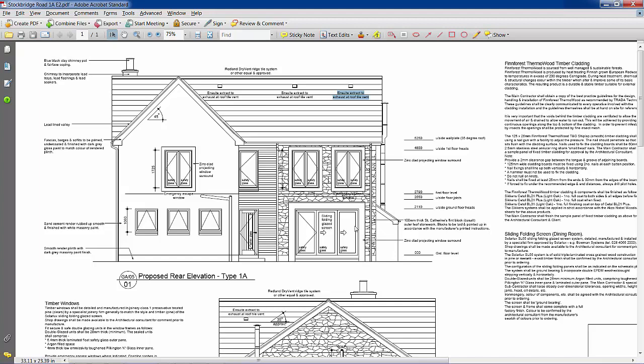We also have sliding doors here at this point, and then notice that on the side we have the rainwater pipes clearly indicated, so the gutter would come along at fascia level and at fascia level here, and then the downpipe has a leg or a bend in it here, and the downpipe in this situation is there and there, so clearly indicate those. We have a set of sliding doors here, so if you have sliding doors, just indicate that visibly in some way.